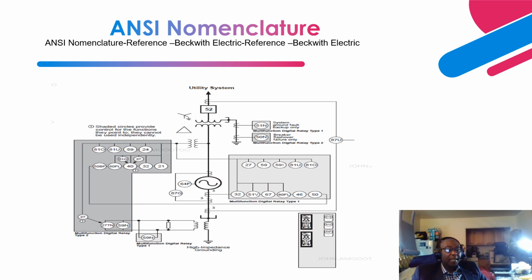Next is 59, and this is an overvoltage element. Let's say you have an overvoltage condition at the terminal of the generator, due to a load rejection, or due to inappropriate operation of the excitation system, or due to inaccurate sensing of voltage. This is the protective relay that will sense it.